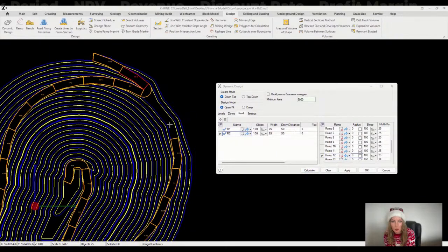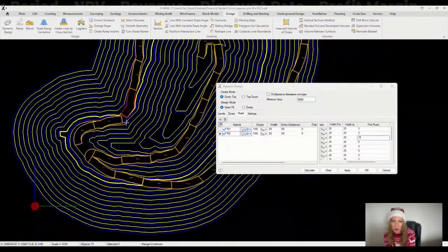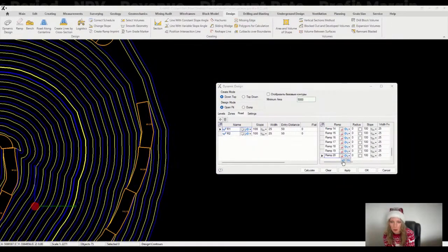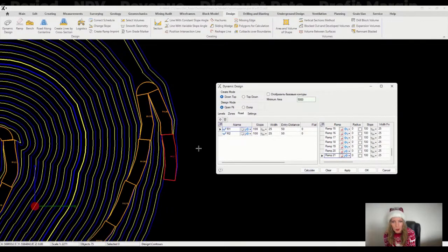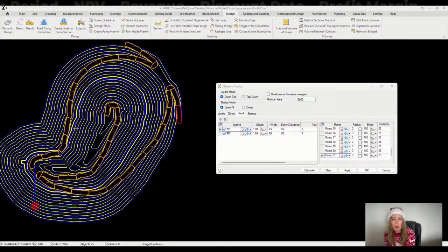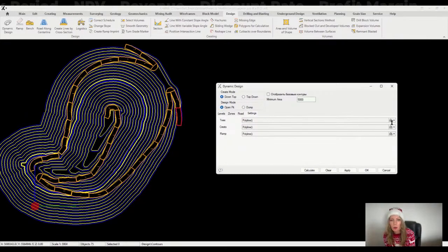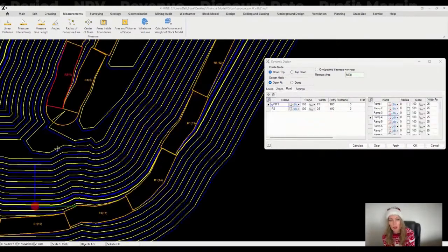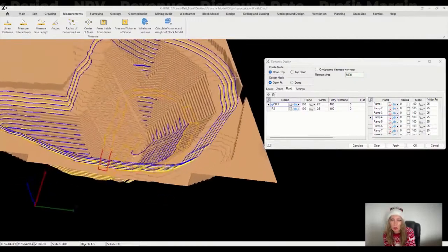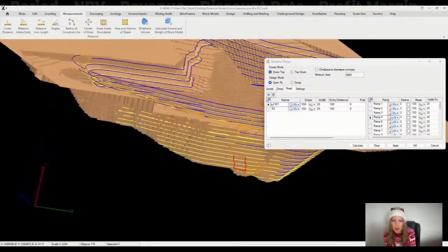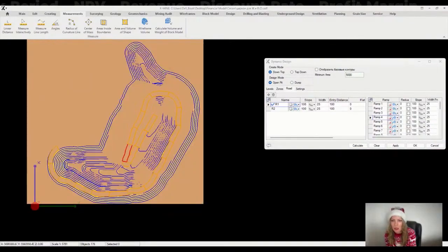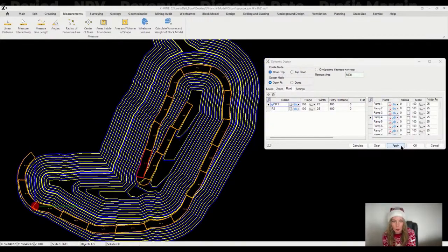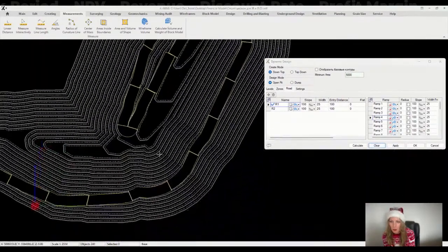Plus, we can put horizontal segments where two ramps meet and widen switchbacks to make sure there is enough turning radius for the heavy-duty dump trucks. So let's add a couple more limiters and change the parameters of the ledges to align our project as closely as possible with the desired shell. And then we'll compare what we've got with what we're aiming for. Once we're happy with how everything looks, we'll move on to drawing up the actual physical lines and make adjustments to any areas that need fine tuning. After that, we're all set to construct a wireframe and calculate volumes and so on.